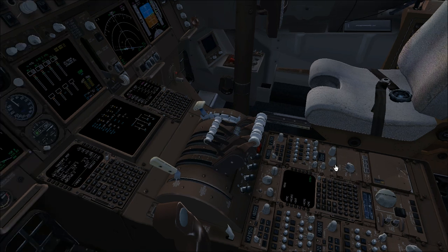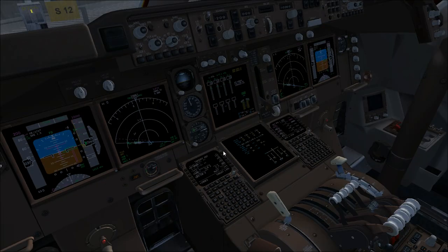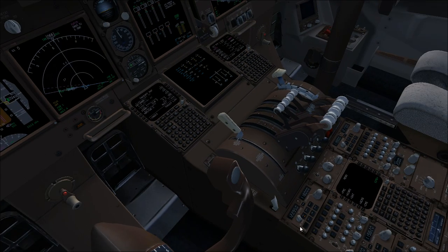Standby instrument must be checked. Altitude indicator caging control is pressed, and we checked it is horizontal. ILS selector for the ADI is off. As you can see, you can select the ILS if you need it. And we set the standby altimeter on 1013, it is actually set. Speedbrake lever is down and checked. Reverse thrust levers are down, and that's fine. And forward thrust levers or main thrusters are closed, actually in idle.